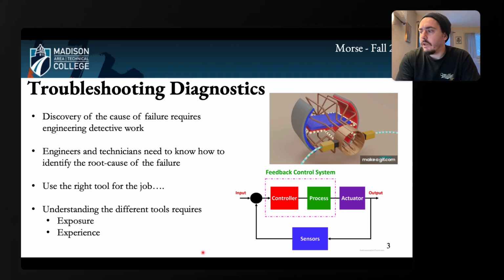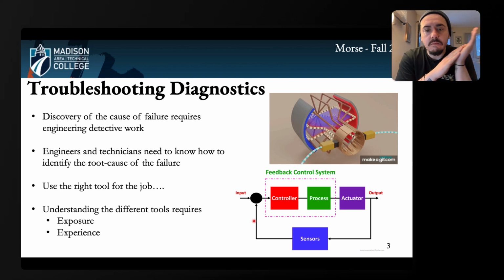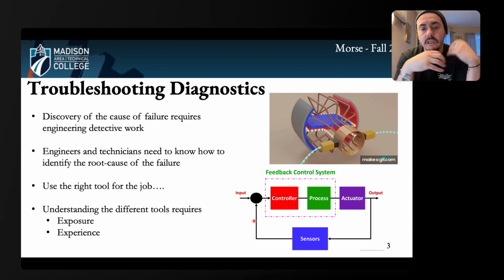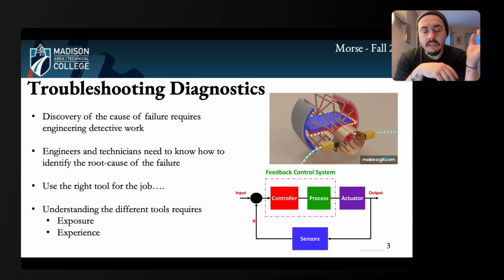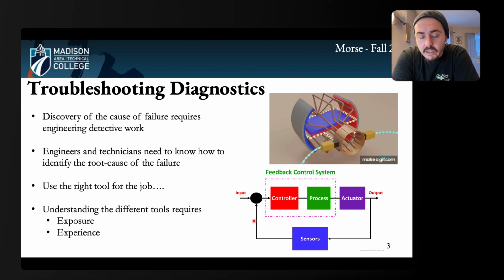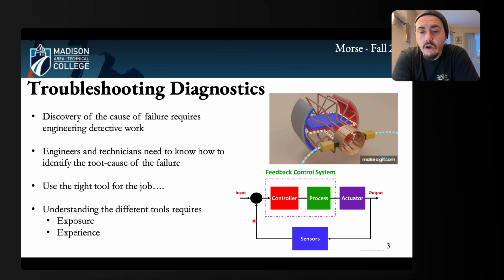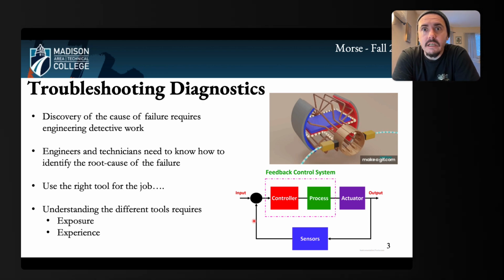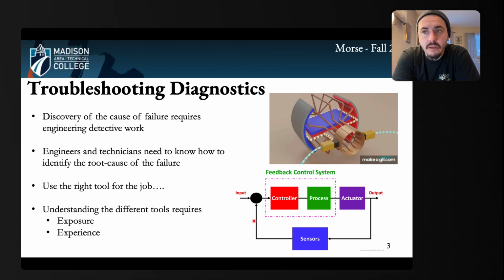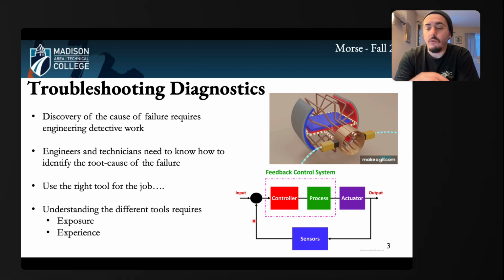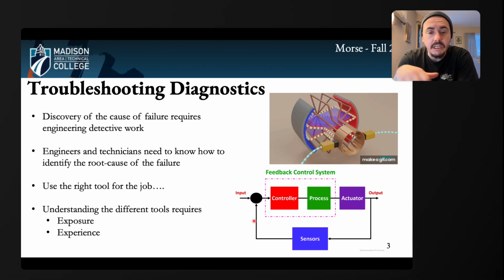One thing I also want to point out too, so most of the systems and most of the components within the systems that we're going to look at have multiple connections. So there's typically some sort of input information. It tells the component to turn on, to turn off, and then oftentimes there's information that's sent back to some other higher order control system, a DCS system. And so when we go to troubleshoot, a lot of times there's multiple electrical leads coming in and out that we're going to have to look at and investigate.